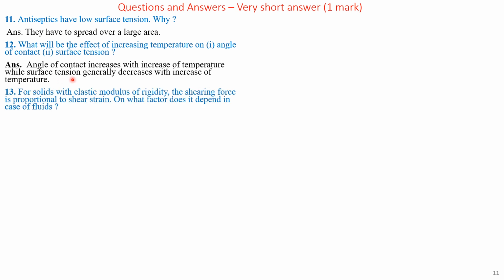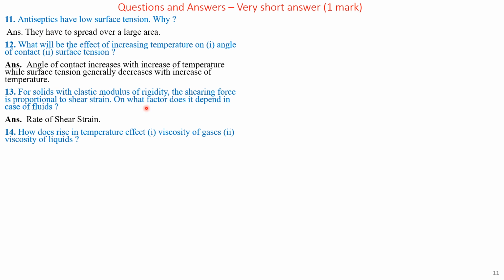Please note it. For solids with elastic modulus of rigidity, the shear force is proportional to the shear strain. On what factor does it depend in the case of fluids? That is rate of shear strain. That is, it depends on the rate of shear strain.